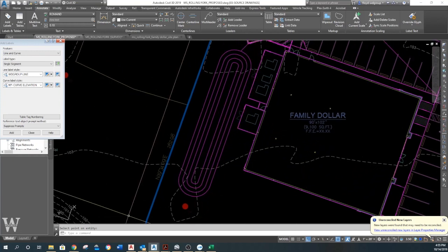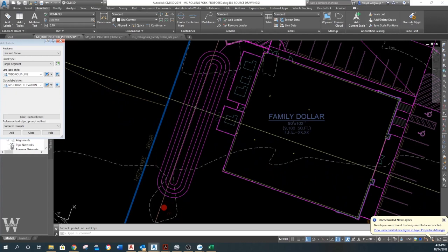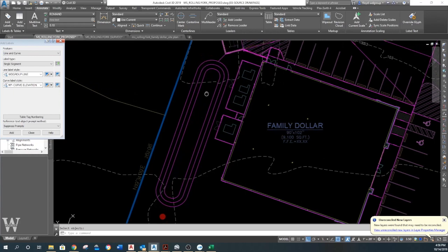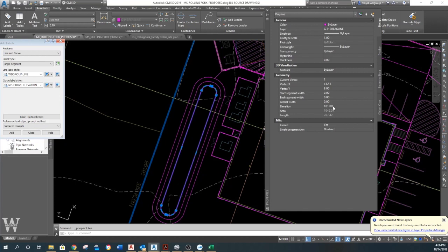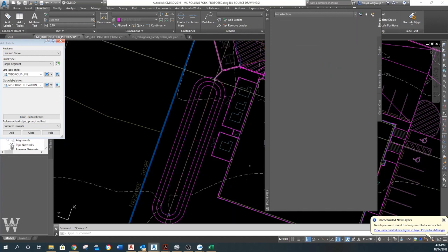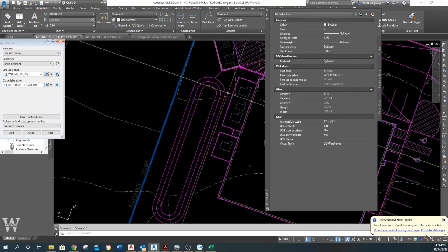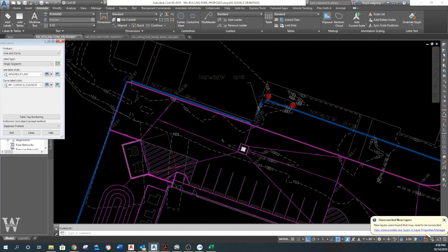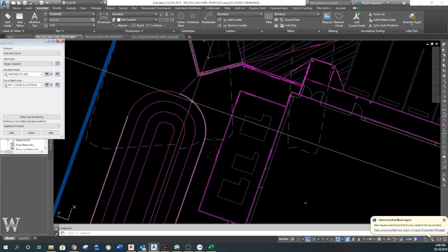So I think based off of my detention pond, I'm going to go back and change this pond. I don't like this pond being this deep anyway. So I'm going to go back and make it 1 foot lower. So I'm going to make this 101. No, I got to have that depth. Never mind. Thinking as I'm going, I got to be at almost 103 so I have cover for my pipe. So I have to be at that. Okay. All right. So I'm good.